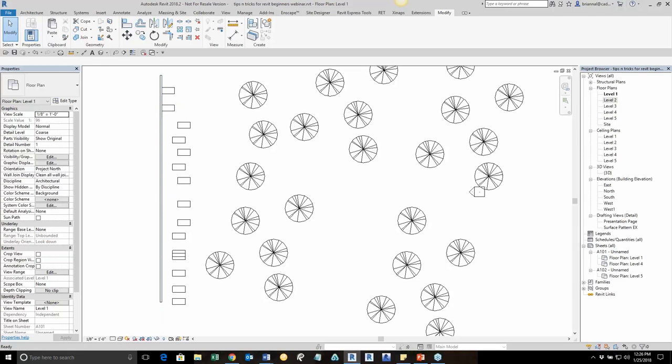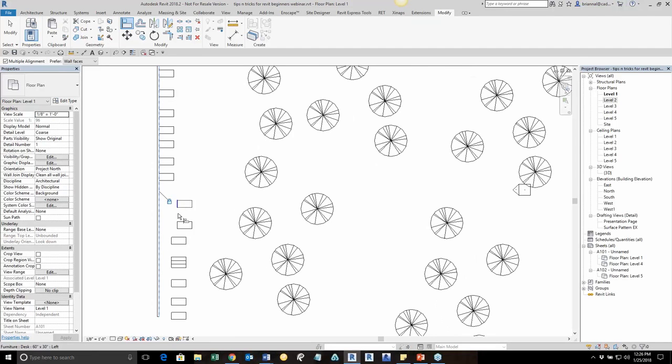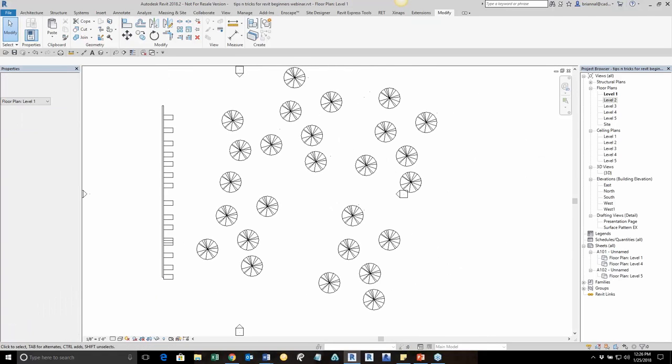So within this tool, the function Align and Lock, there is this ability for multiple alignment. So if I check box that, then I just have to select my element, and then I can continue on in a nice, easy, little bit faster way, saving me a couple of clicks, with the ability to align all of these items right in a row, saving a click back and forth from the original align to element.